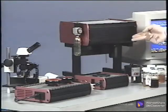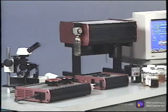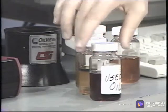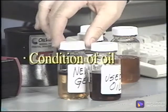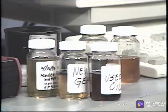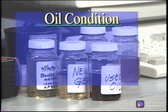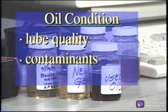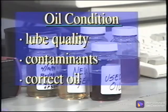These devices here are tools commonly used for on-site oil analysis. Each of these is designed to provide particular information about the oil. There are two categories of information testing provides. One is about the condition of the oil itself, and one is about the condition of the machine. For the oil, you want to know the lube quality, including the condition of any additive package, if there are any contaminants, and whether it is the correct oil for the particular application.